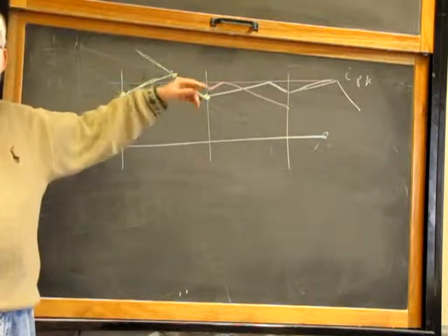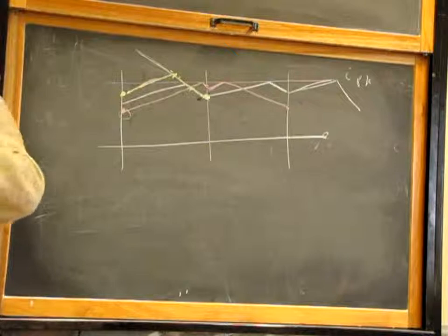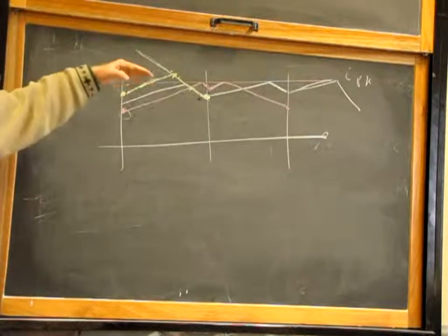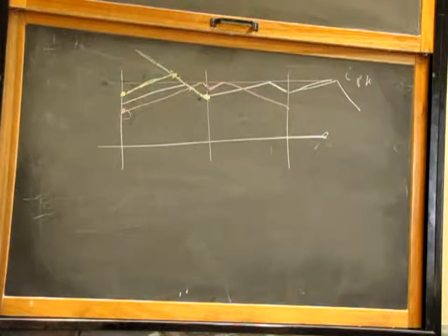What about this error? This error is compensated by the integrator that just changes the peak value in order to get exactly what I want. So compensation ramp is needed, is a must, every time your buck-derived converter works with a duty cycle that is larger than 50%.